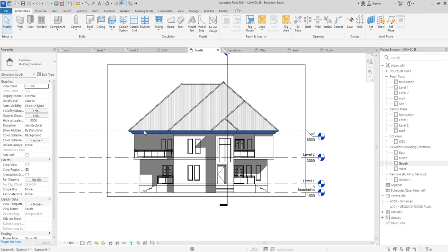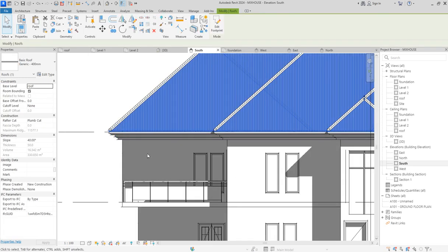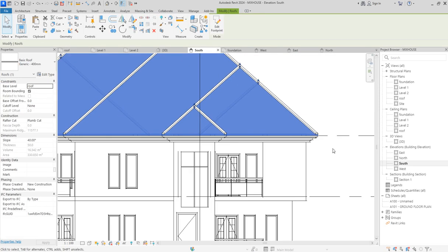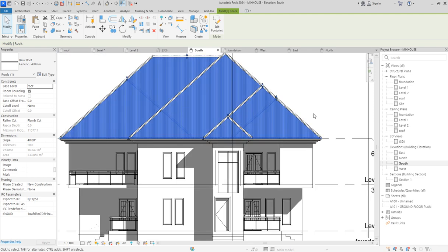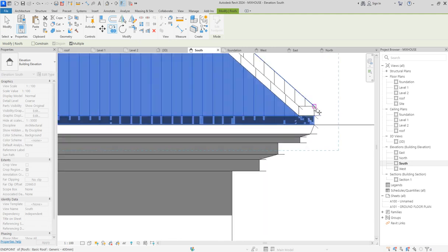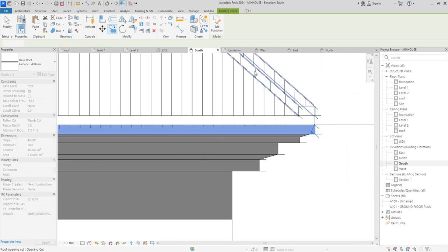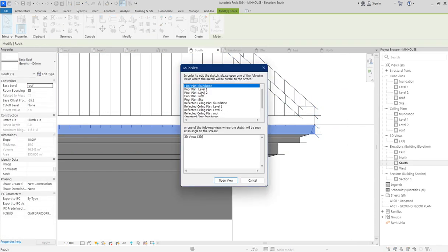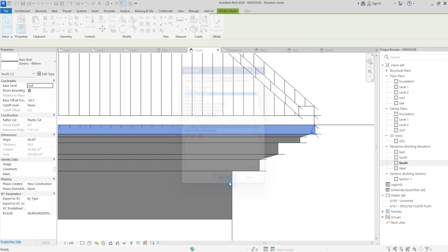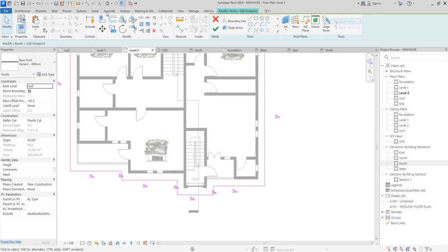With this one now, what I need to do next is create the trusses. I didn't have the trusses before, so let me do that quickly before I proceed to the next thing. So you copy this roof, paste it down here. Then you say edit in place, edit here again, and just open that. Then you offset this inside by 200, not 300 or 200. You should do okay without copy.